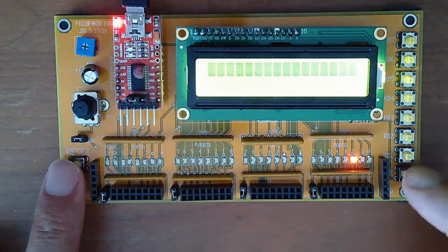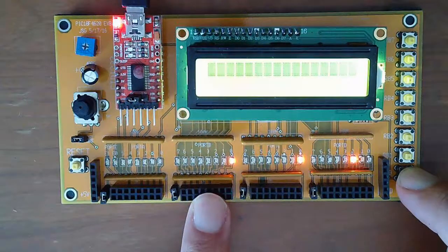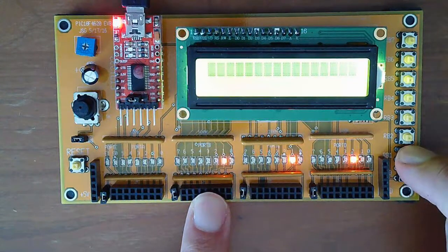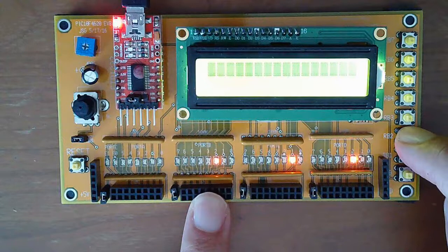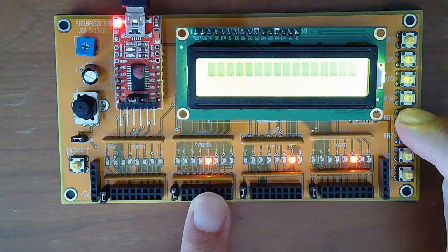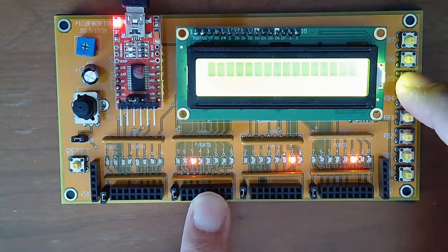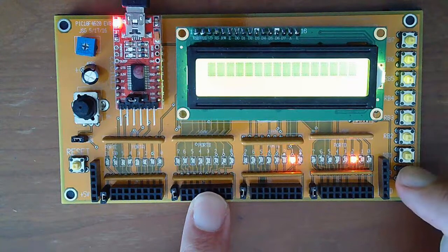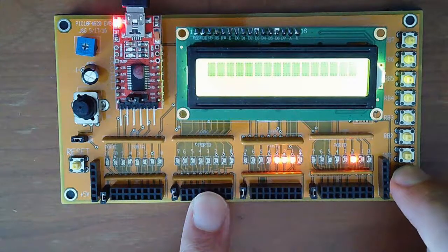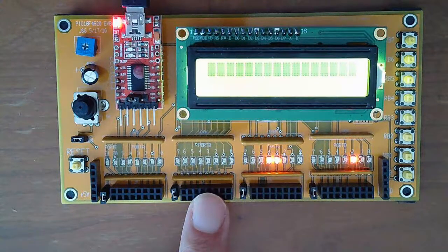So when I hit RB0, notice that the light turns on port B. That means this pin is input, and all of port B is input. So there's pin 2, here's port B pin 3. If I go to port B pin 0, I'm counting the rising edges on port B pin 0. So there's 3 pushes, 4, 5, 6, 7, whole bunch of pushes. That's my counter.